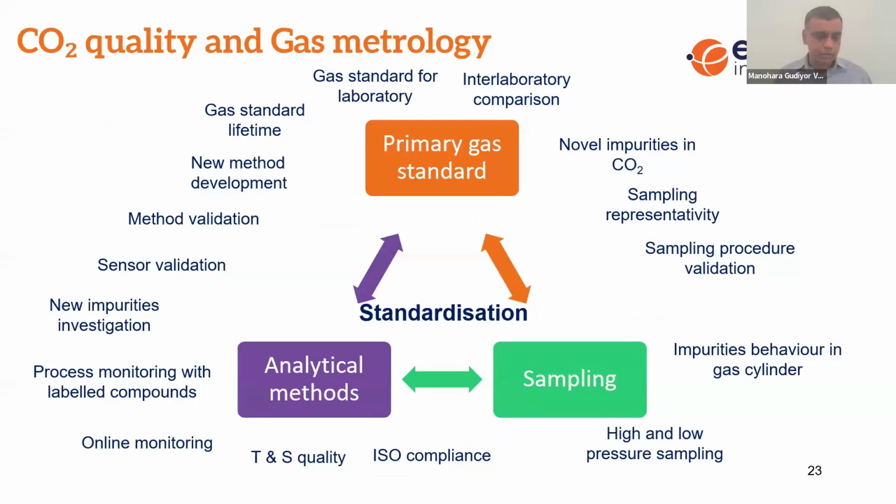I will build on what Gordon explained, how sampling is very important in order to get a homogeneous, representative sample. So I will build on that and explain how to get accurate measurement of CO2 and how gas metrology supports accurate analysis of CO2.